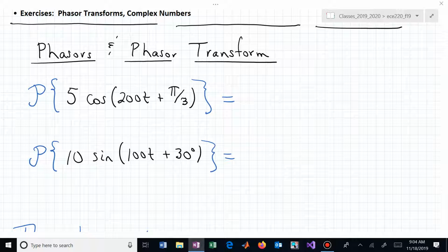We have 3 quantities floating around: a magnitude, a frequency, and a phase. We actually put the frequency on the side. We just need to keep track of that. If we're talking about sinusoidal steady state, everything is now oscillating at that frequency, and we can keep that on the side. And what we're interested in are the magnitudes and their phase shift or time relationship.